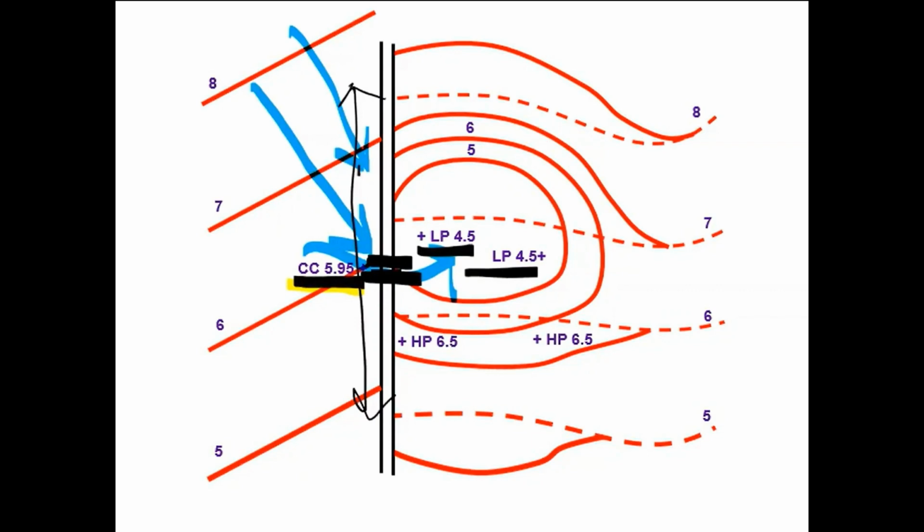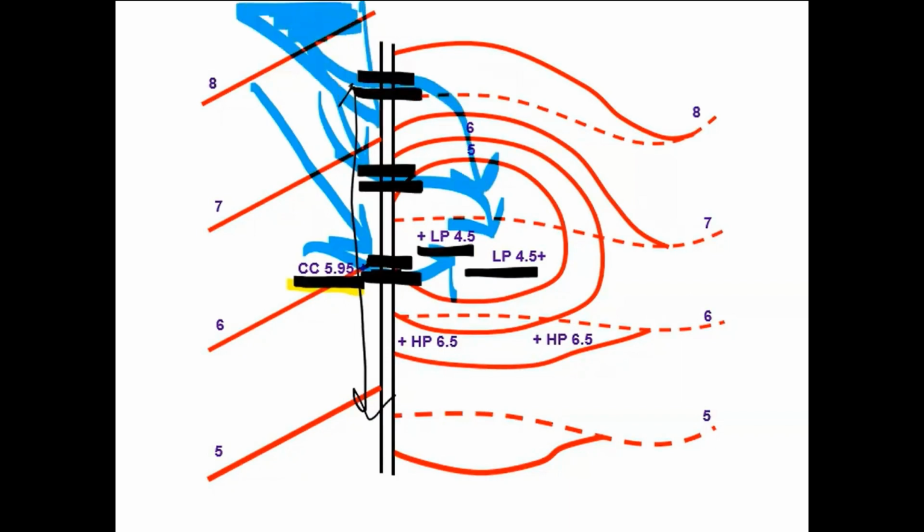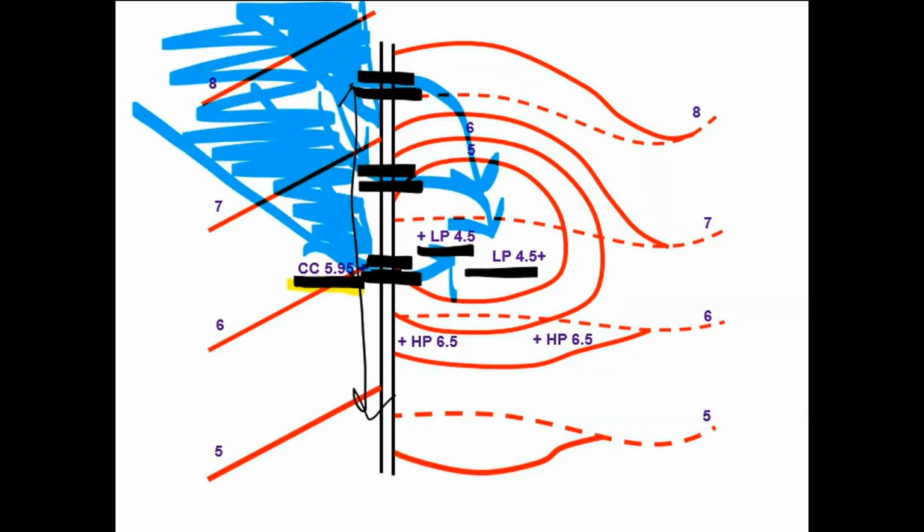We could actually locate that curb cut further up if we wanted, and water would still flow through the curb cut into the retention area. We could even locate it further up the hill if we chose, and water would still flow into the system. Of course, what would happen is that the area that's flowing into it would be a smaller area than the area that's flowing into it as we locate it further down.